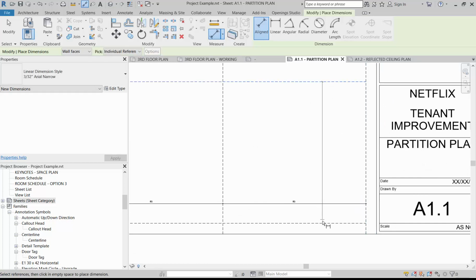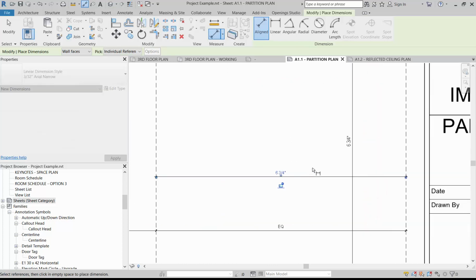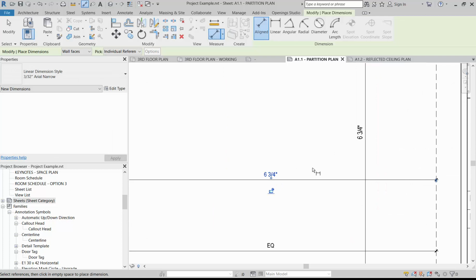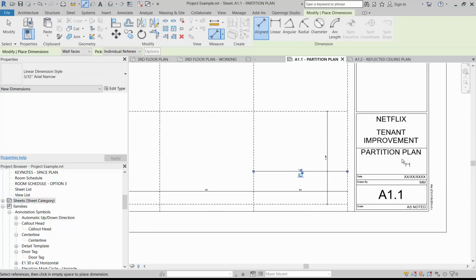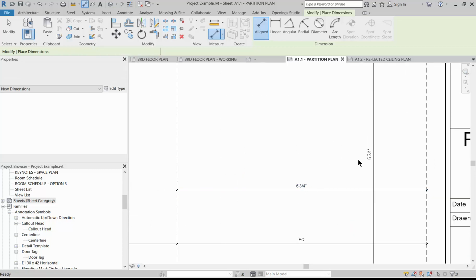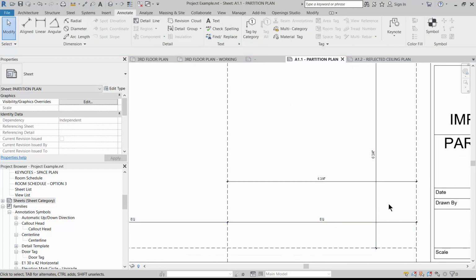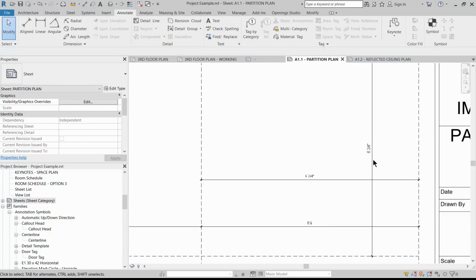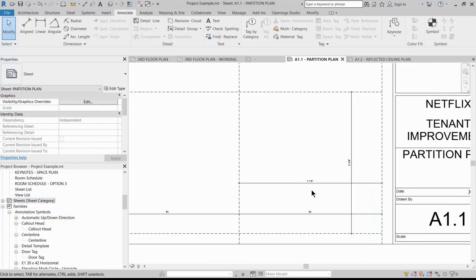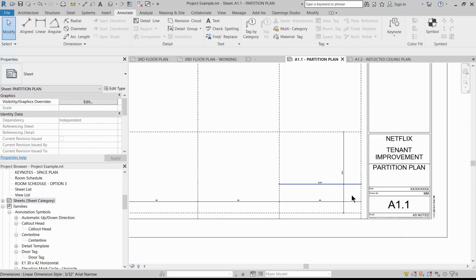Now if I dimension this box, it's going to be 6 3/4 of an inch vertically and 6 3/4 of an inch horizontally. So this is one of the reasons I told you not to mess with the proportion of the tile block, and if you do, you might need to adjust the offset lines, because by keeping it to this dimension and then we just offset 1/2 inch evenly throughout, this is going to give us a very clean dimension for evenly shaped square.